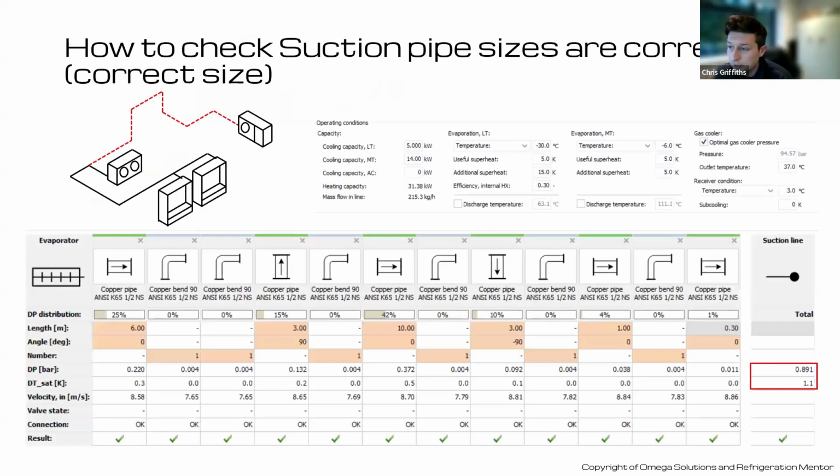So Danfoss allows you to put each individual section of that pipe into play. So we can start with a horizontal section, followed by a 90-degree bend, another 90-degree bend. So that'd be for the bottom of our riser. A vertical section, top section where it tops out, horizontal, comes down, along, down, along, etc. And based on half-inch pipe, this gives us a total pressure drop of 1.1 as we looked at earlier. How easy is that?